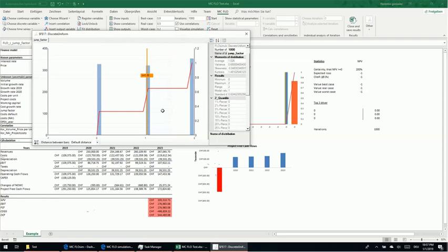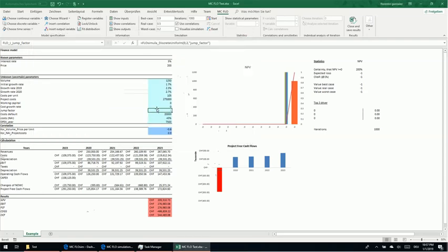You can see this variable has been locked with the expected value of 1. We can unlock or lock specified variables. Now we start our simulation, not with the input variable, but for the entire model.